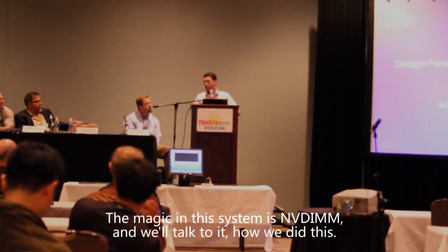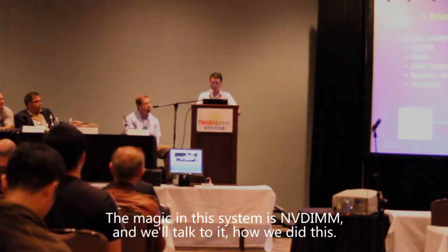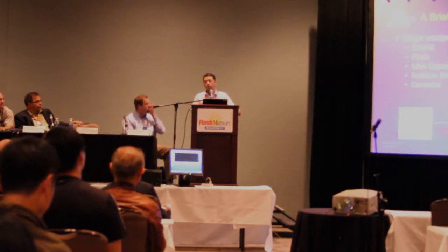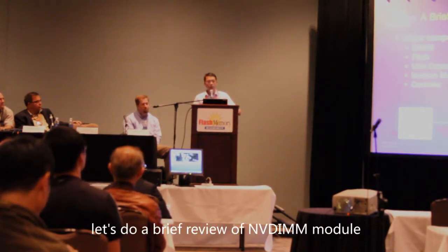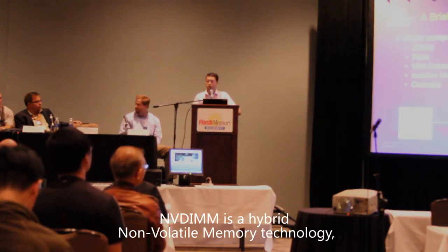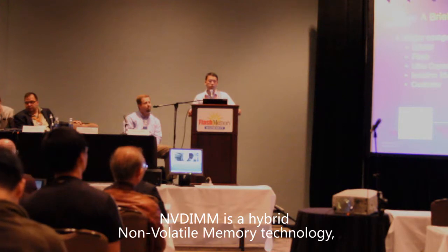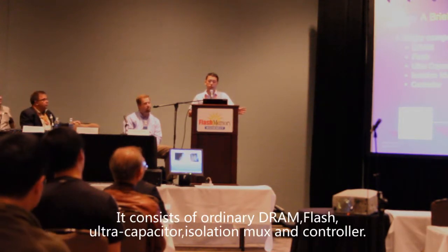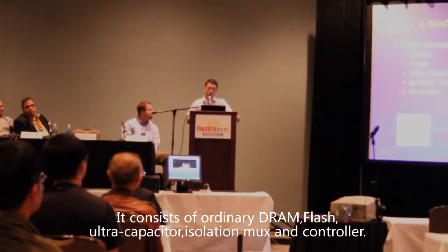So the magic in this system is NVDIMM, and I'm going to show you how we did this. For those of you who are not familiar with NVDIMM, let's do a brief review of the NVDIMM module. NVDIMM is a hybrid non-volatile memory technology. It consists of ordinary DRAM, flash, ultra-capacitor, isolation mux, and controller.